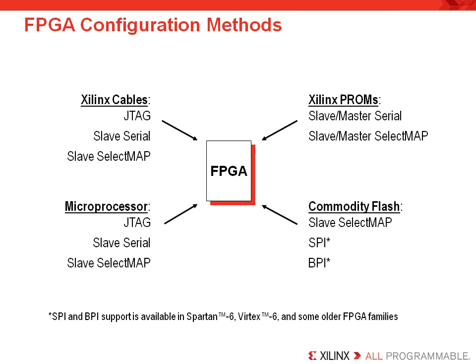Configuration also can be completed using the Xilinx Platform Flash PROM. These configuration schemes usually use the FPGA's built-in configuration logic to control the FPGA's configuration process. With these components, the FPGA usually configures itself. These configuration schemes require the user to buy a PROM, which has some additional cost, but these schemes are usually the easiest to debug since the control logic is already fixed as part of the FPGA. We will talk about the Xilinx Platform Flash products in the basic FPGA Configuration 2 module.